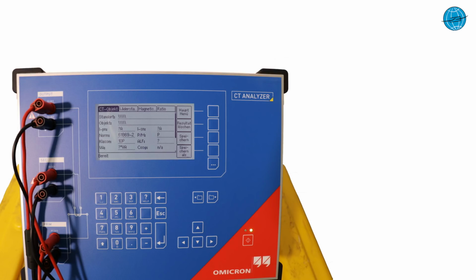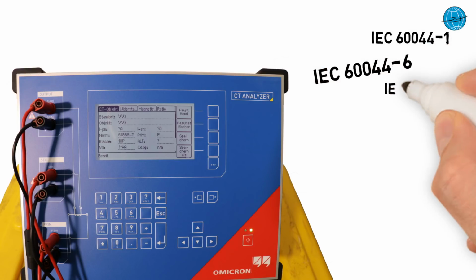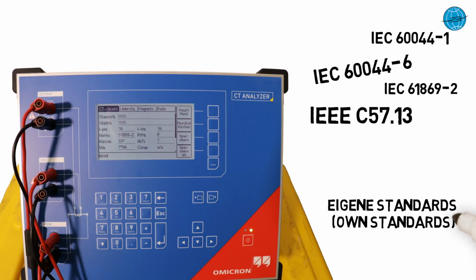The CT Analyzer automatically detects all relevant CT values and compares the results with the selected standard. The device evaluates the current transformer according to IEC 60044-1, IEC 60044-6, IEC 61869-2, IEEE C57.13 or national or self-defined standards within a few seconds at the touch of a button.